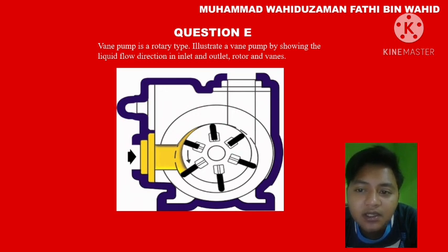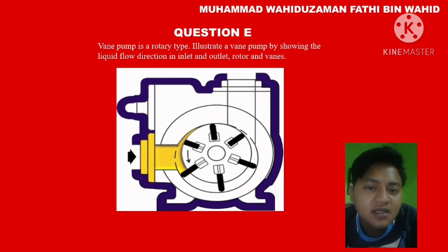The housing and cam force fluid into the pumping chamber through holes in the cam. Fluid enters the pocket created by the vanes, rotor, cam, and side plate. As the rotor continues around, the vanes sweep the fluid to the opposite side of the crescent, where it is squeezed through discharge holes of the cam. As the vane approaches the point of the crescent, fluid then exits the discharge port.